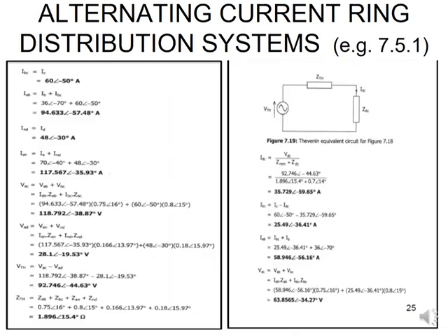So here they are, as I have said there before, they are just doing those computations. Once that's done, then you can calculate the voltage, and the voltage is between your VAB and your VBC because they want to know our AC. So now that you've got those 2 voltages, because you know what your IAB and your IBC are, you can calculate that voltage is 118.792. Then they calculate the VAD, and the VAD is then your VAN plus your VND, and you get that voltage.